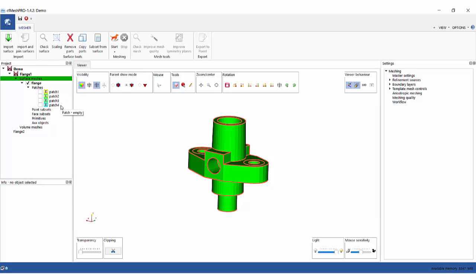The purpose and most important use of patches is in marking off the simulation domain boundaries. Within the simulation context, the patches usually represent, in a meaningful way, the domain boundary sections, where boundary conditions are imposed. As such, there is a restriction that the patches must not overlap. Within the meshing procedure, patches identical to those on the surface mesh are automatically created on the volume mesh.